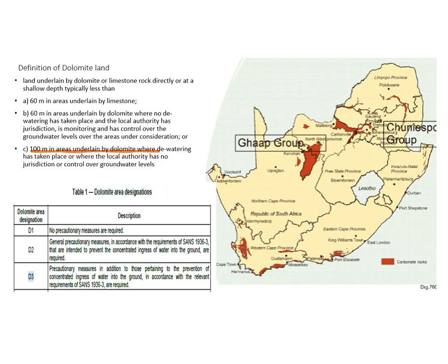Dolomite areas are categorized, and this is the way I try to explain it to myself. It's categorized by people that do special reports, geotechnologists, and it's covered within certain levels of risk. As you can see in the bottom left-hand corner, dolomite areas are given a designation. If it's a D1 area, there are no precautionary measures required.